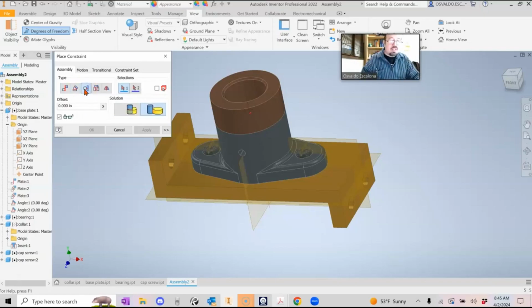Tangential constraint is when you have something that is circular, and then you want it tangential to a surface, or maybe tangential to another circular part. This one is the insert, and then this guy is the mirror. Like if you want to have a plane and you want to make sure that it behaves in a mirror fashion between 2 components and a mid plane. This one is actually not commonly used, but these other ones we can actually talk about, right?